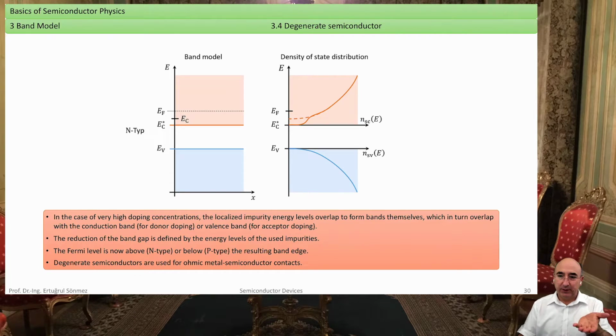But if you have a semiconductor which is doped and say, okay, I place a metal on top of it, and then you expect that the semiconductor is conductive through the metal to the semiconductor, it's not really true. It is conductive in one direction, and in the other direction, it blocks the current.